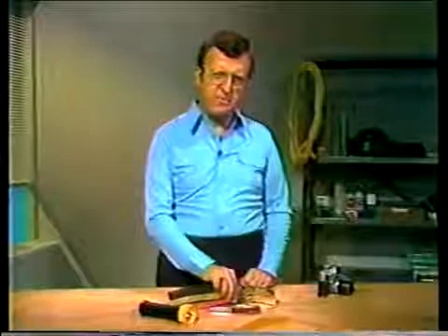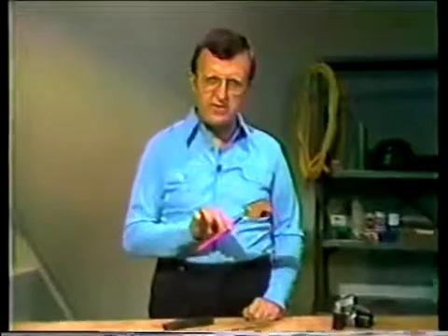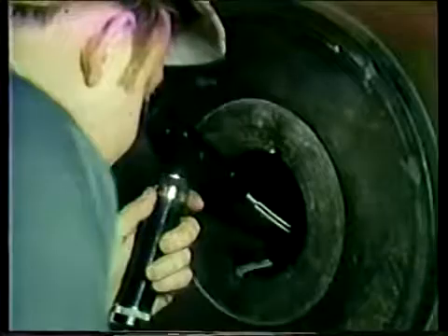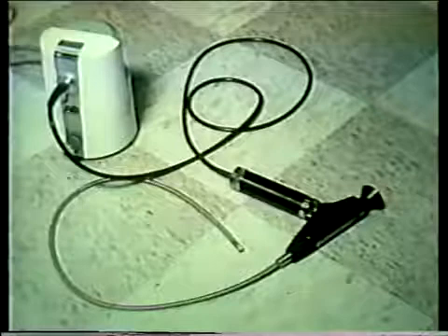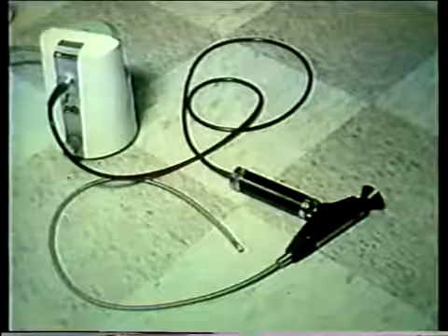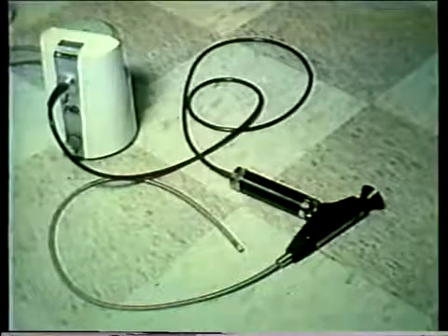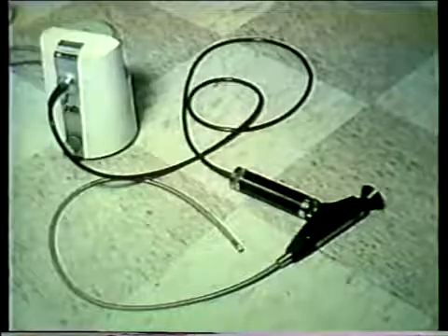The inspection mirror allows you to see some hard-to-get-to places in the boiler, but there will be places where even your mirror won't help. And in these places, you can use a borescope, which is an instrument that uses fiber optics. A fiber optic is a glass fiber that lets you see around tube bends and into other tight places you could not normally see.